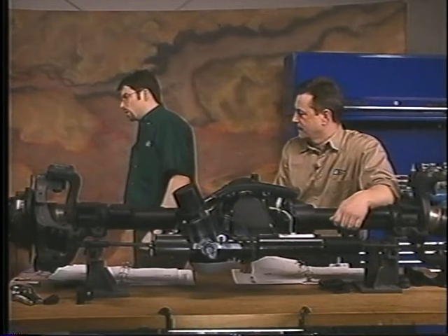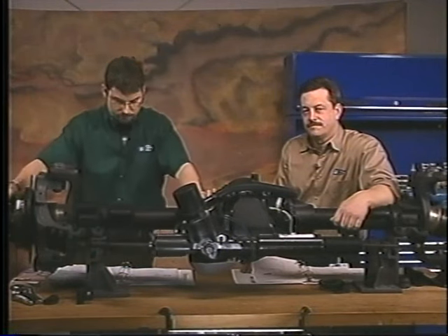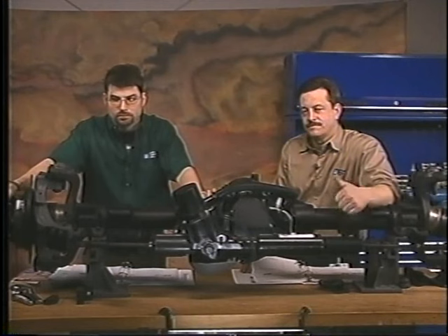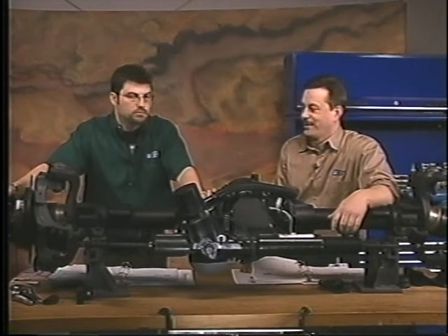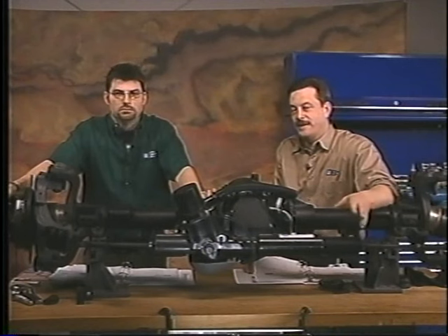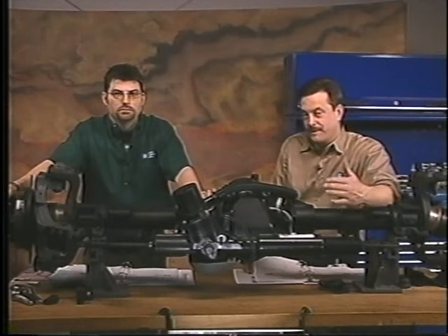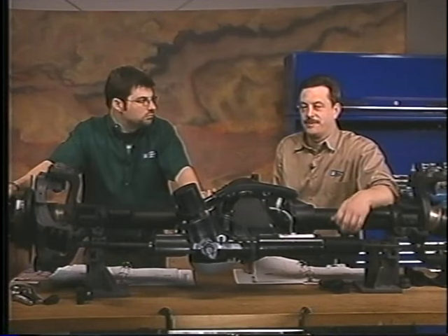Okay, next we have Cody. Cody, go ahead. It changes phase at lower speeds. There we go. That's what we're looking for. Kind of simple, kind of straightforward. We're going to change the speed where we go from negative to neutral and then to positive. Remember before we were talking about 45 miles an hour for that crossover. That's going to change. Now it's going to be 25 miles an hour.